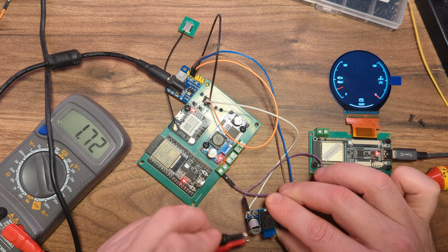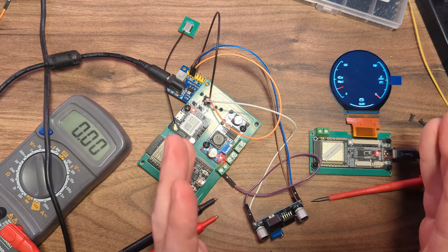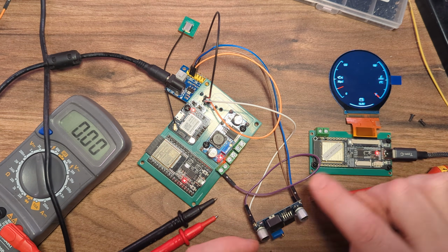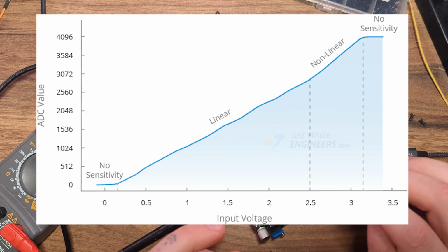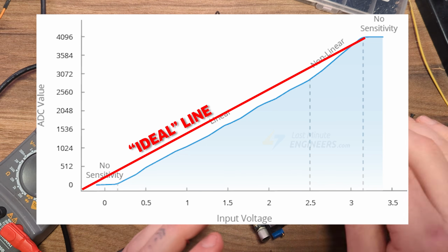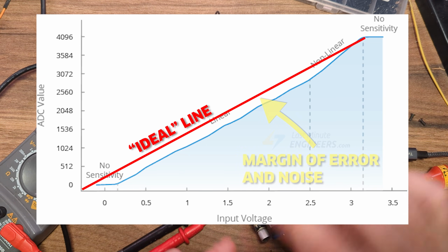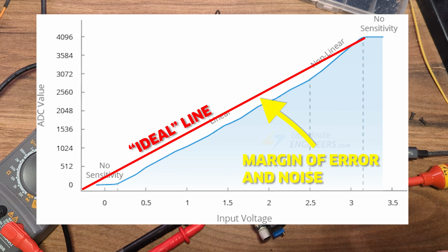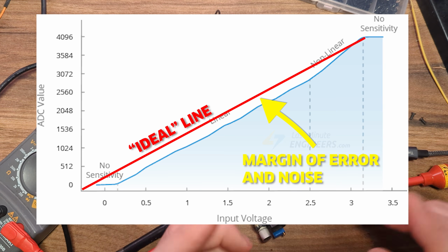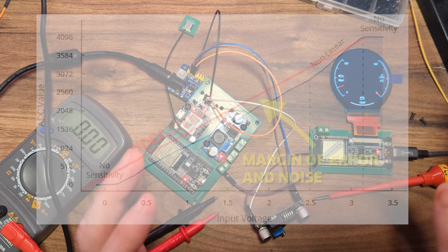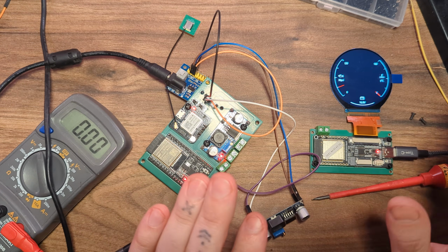1.72. So again, everything's a little on the high side. Now, there are reasons for this. Potentially, the ADC converter isn't perfectly linear. It has a habit of being slightly over. So I might need to do a little bit more compensation, or there are some libraries that smooth out that ADC line a little bit better.